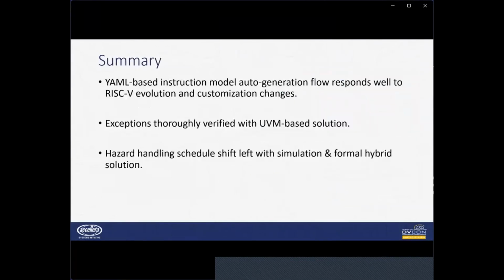The last part is a summary. In this paper, we demonstrated our YAML-based instruction model auto-generation flow, which responds well to RISC-V evolution and customization changes. Our exceptions are thoroughly verified with a UVM-based solution. Verification schedule shifts left with a simulation and formal hybrid solution. And that's all. Thank you.